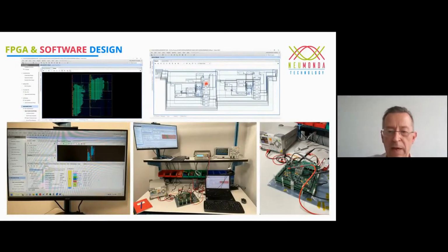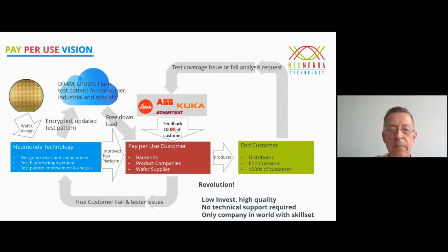Certainly our FPGA, our design has to be improved. Patterns can be programmed into the FPGA. So you have to do a lot of work on FPGA design and controlling the memory controller on the FPGA, because you want to make sure what pattern physically you exactly write onto the DRAM, so that you can also do technology pattern testing and verification, which is not possible with this CPU approach.